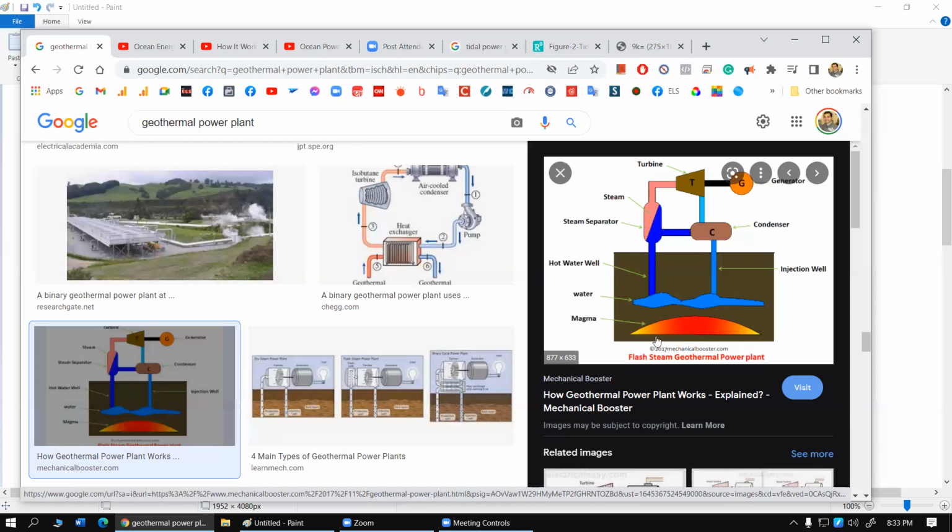This steam production is going to happen by this heat source, and there will be a steam separator which is going to take only the steam and then blow it onto the turbine, hot steam, and the remaining water will be fed back to the condenser. As the steam will enter into the turbine, it will give out its kinetic energy to the turbine, but it can never give out 100% kinetic energy.